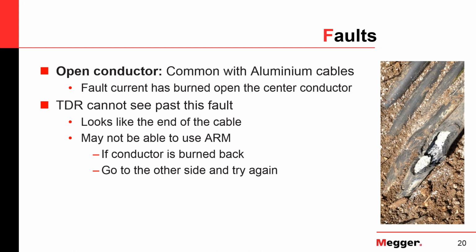And the typical solution in the practical world would be, okay, if you limit it to this point, just go to the other end of the cable, because typically the cables, as we discussed, are isolated, grounded, stood off, parked. So you can go to the other side and try your fault location techniques from the other side and hope to learn more.